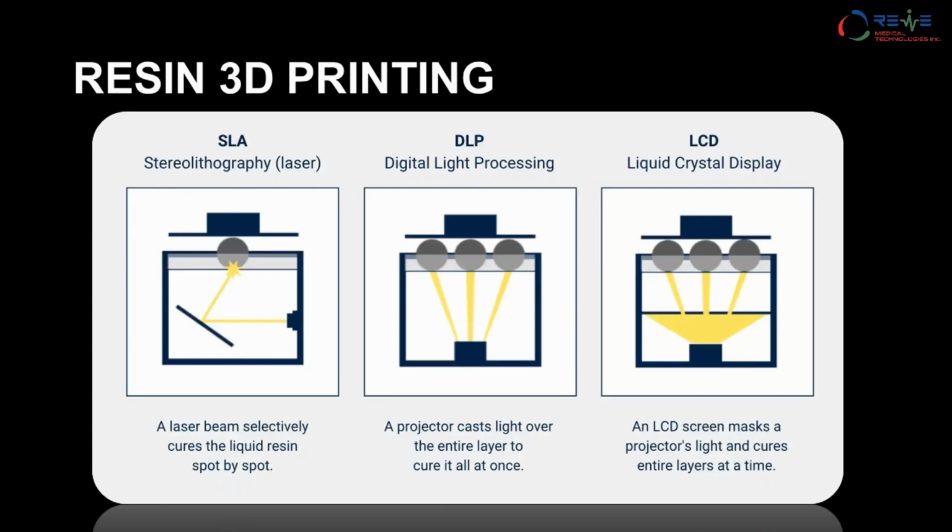There were very selective companies. Formlabs is one of the very popular companies these days. They made their SLAs, but this technology needed to be made more cost effective. So in came LCD 3D printers. Rather than using a laser to move it, they placed a whole LCD underneath the bath, and the LCD would light up in the way the design was, and it would layer by layer cure the design.